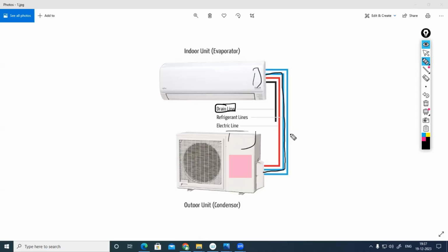Condensate. We used to call that the condensate drain line or condensate drain. Below the indoor unit, we'll be having a condensate drain tray. The condensate drain tray will come just below the evaporator coil. At the end only, we will be connecting this condensate drain pipe. Because when the AC coil is removing the room latent heat, the moisture from the vapor goes back to liquid. That's why water is produced. It depends on the humidity level within the space: more water will be condensed if the humidity is high, and the process will be less if the humidity level is low, right?